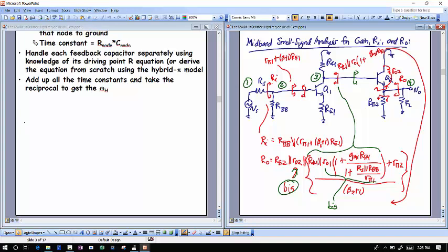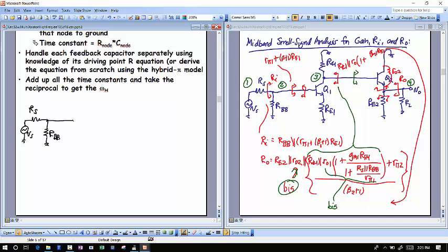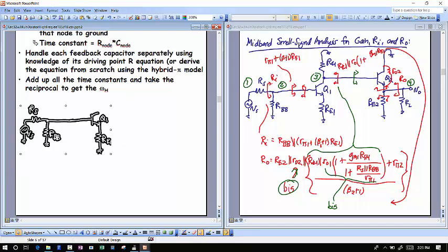And the difference this time is I'm going to put in all the little capacitors that I'm going to have to deal with in this circuit. So right now I'm just redrawing this. So I got RS, RBB, that, and I'm leaving a lot of space here because I'm going to put a lot of capacitors in there. That's going to Q1. The small signal circuit had this RE1 that stayed back, or that stayed there because of the way that I chose my bypass capacitors.